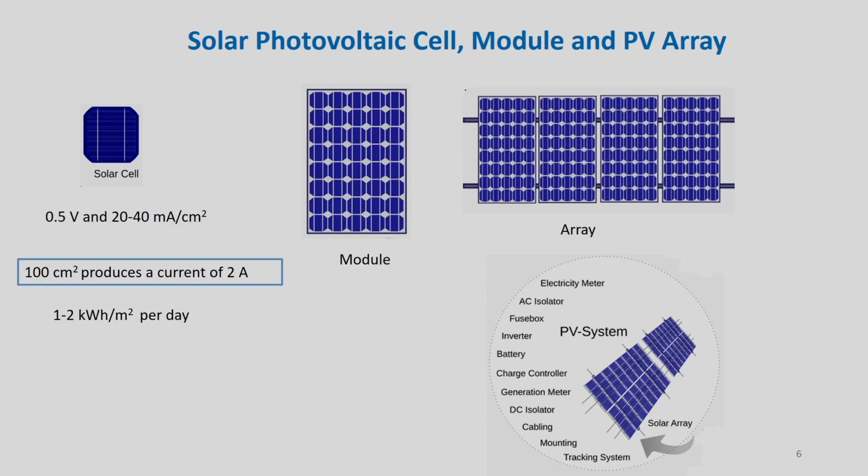Okay. So in street lights our requirement may be one CFL, and then if we are using a battery, battery voltage may be 12 volt or maybe 80 ampere hour. So it is something like that. So in order to power these 12 volt batteries, we can decide the number of cells to be connected in series. Okay. So when these cells are connected in series, then what we are doing? We are maximizing the voltage. When these cells are connected in parallel, then we are maximizing the current. Okay. That way you can decide.